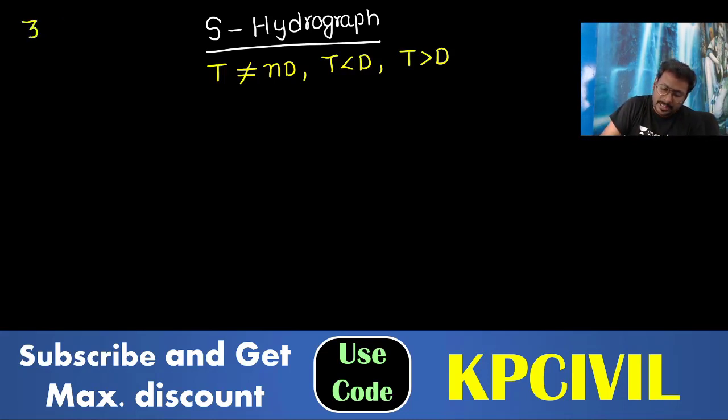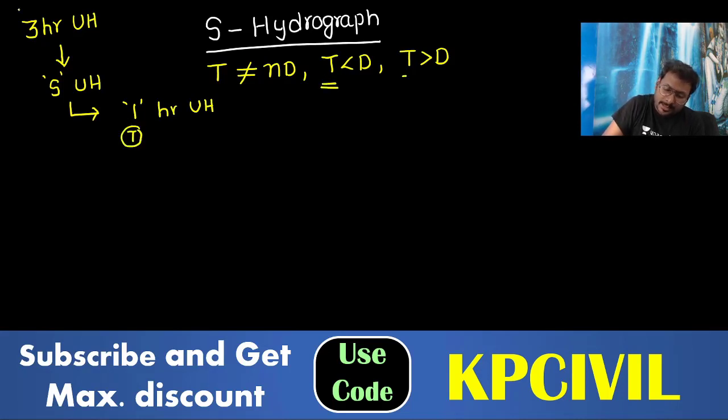For example, a 3 hour unit hydrograph is provided to you. Now you first plot the S hydrograph. Convert this S hydrograph to a 1 hour unit hydrograph. So T is less than D, right? T is 1 now, D is 3. You can accept 3 hour unit hydrograph to S hydrograph, S hydrograph to 1 hour unit hydrograph. Possible, right? So that is done.